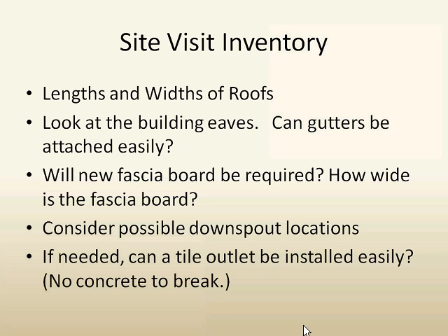Consider possible downspout locations. Remember, you've got to bring that downspout down and you've got to attach it to something. So if you have long open spots, or limited posts, like that one picture that I showed earlier, you want to make sure that you're taking that into consideration when you're designing your downspouts.